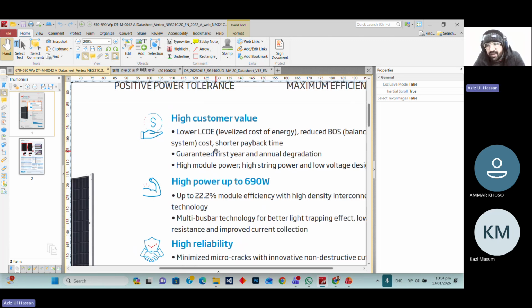These factors will be different for different PV modules. The P-type PV module has a different LID factor, and the N-type PV module has a different one. Basically, the P-type PV module will decrease 2% in the first year, but the N-type will decrease 1%.